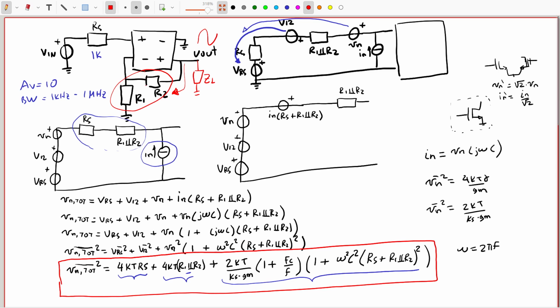If I use very small resistors, then I will need a large current at the output just to be able to drive those resistors. So I have a limitation already there: reducing the input referred noise coming from the resistors will cost some current. So it is possible to reduce, but I will have to put a lot of current at the output in order to drive those resistors.